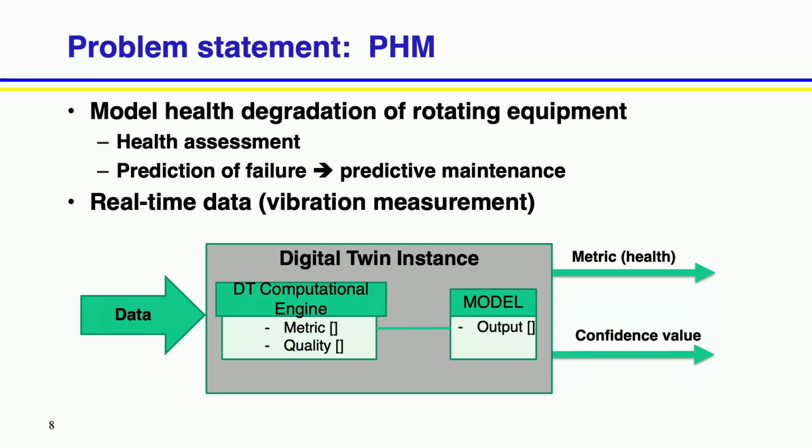So is the motor healthy, or is it starting to degrade, or is it likely to fail? And how much time do we expect before it's going to fail? Because if we have that information, we can think about whether it would make sense to take that down tonight or next weekend, or whether we're going to run it to failure. And that information can be useful for the operator.